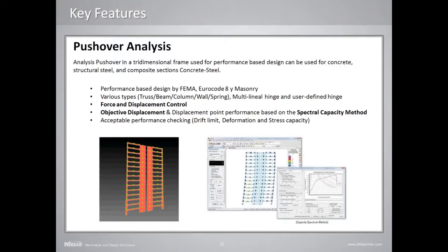For seismic zones, we have pushover analysis. Pushover analysis can be performance-based, and by FEMA and Eurocode. As you can see here, we also have force and displacement control and objective displacement for design.